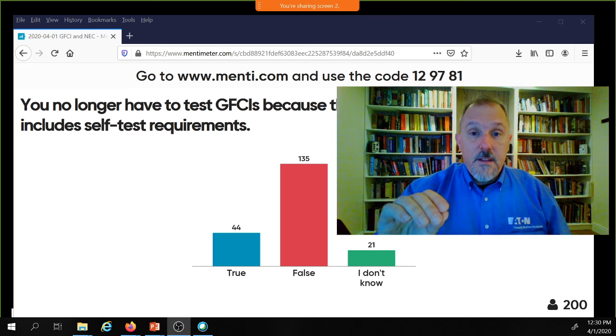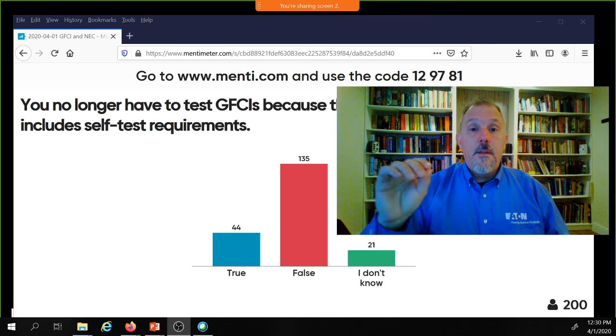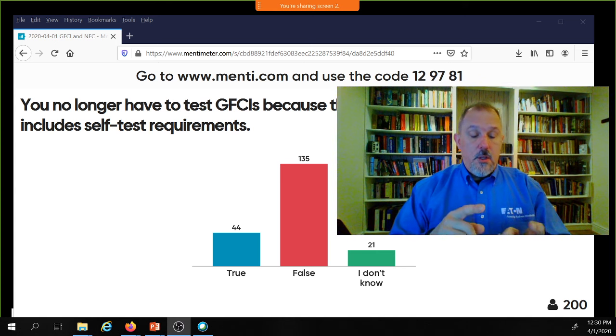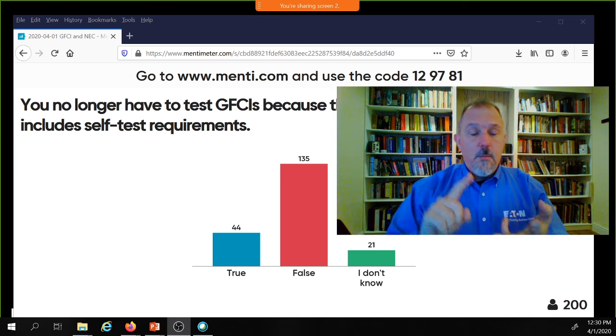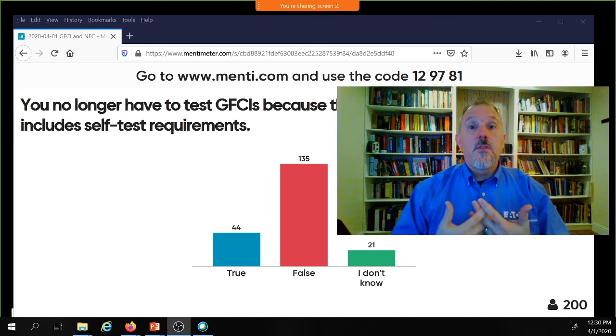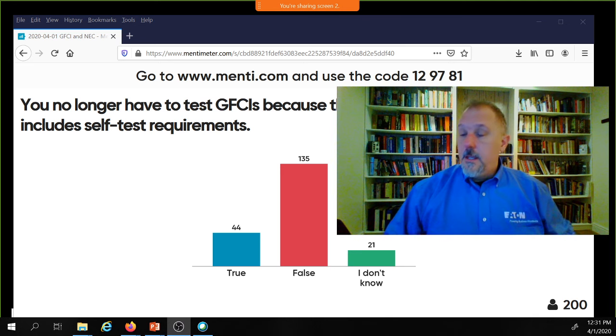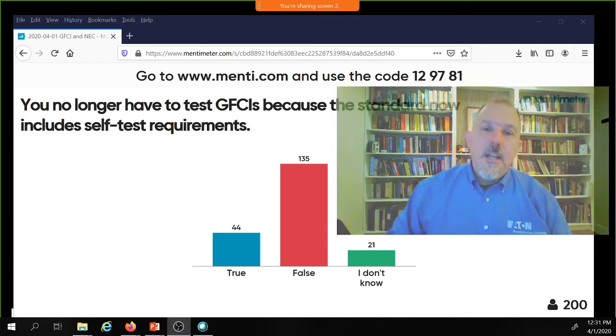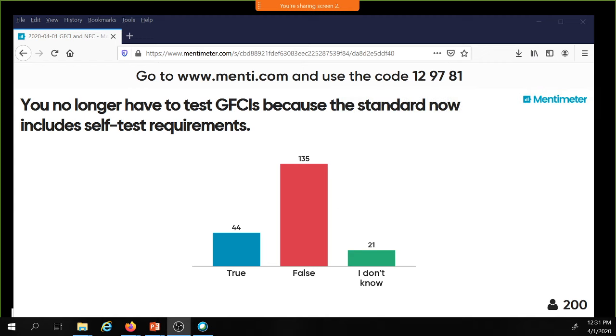But now, here's my advice. Never trust whether or not that device has been tested monthly. In any place, in a hotel, in your home, no matter where you're at, push the test button before time of use. That will ensure that it's working and functioning for you. Okay, so that's just a little tip. Number 1 is test before use, but you're supposed to press the test button.